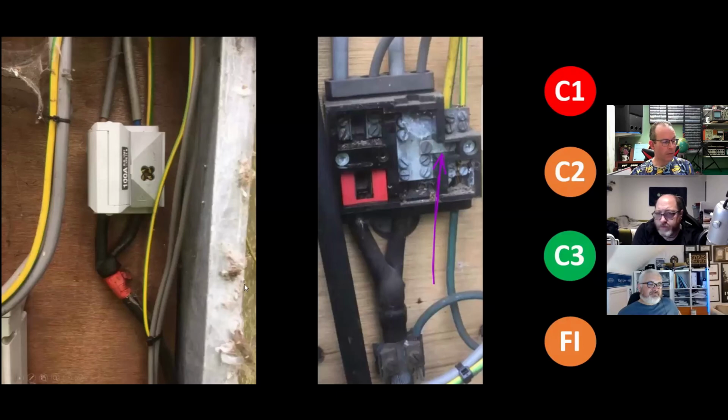Yeah, interesting. But that one on the right, I think, is the main one for me that's quite important: that connection there. There are millions of these. I've worked on so many installations where I've connected into that terminal, not realizing that there could easily be a link inside. I've always defaulted that they are PME because they're next to the neutral. They're on there with the neutral.